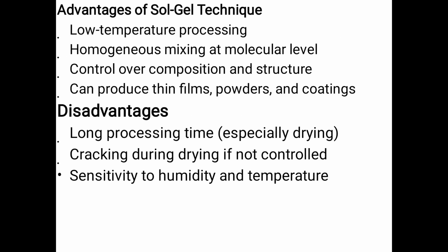Advantages of the sol gel technique. Here low temperature processing is only required and homogeneous mixing is obtained at a molecular level. Control over composition as well as structure can be obtained, and they can produce thin films, powders as well as nano coatings.